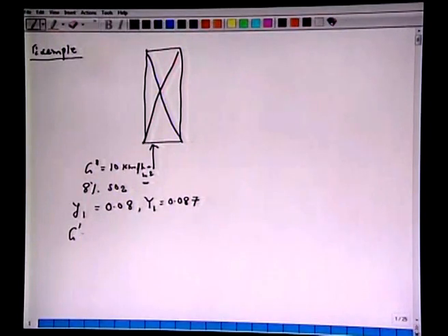So, we can have the molar flow rate of the solute free basis as G prime (1 minus y1) equal to 9.2 units. These units are the same as what we have written here, kilomole per hour per meter square.